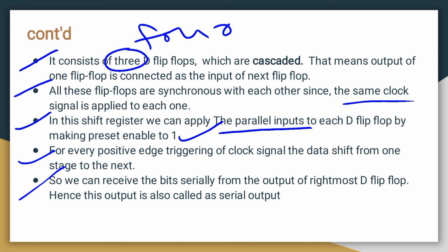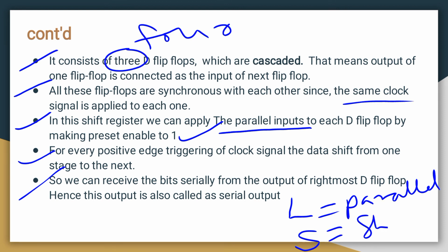So in this slide I didn't point out the load and shift, but when you are explaining in the examination you have to concentrate on load and shift. So you have to write that for load all the parallel bits will be stored in the flip-flops. For the shift it is going to be shifted from one flip-flop to another. Okay.